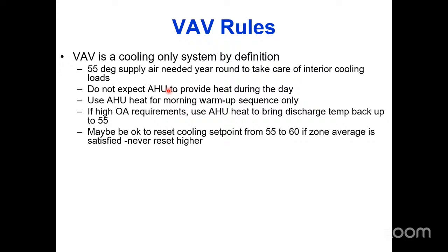The reason occupied heating is on the dip switches and available to be done is because people asked for it. And factories are not smart and they give it to you, even though you don't really know what you asked for. The only real use for it is construction mode, right? The building's not occupied yet. I haven't even installed the VAV boxes. I don't have any computers. I don't have any servers. I don't have any load. Like, yeah, I might need some heating just to get the building functioning in the middle of the winter, right? Until it gets fully occupied. That's its purpose in life.